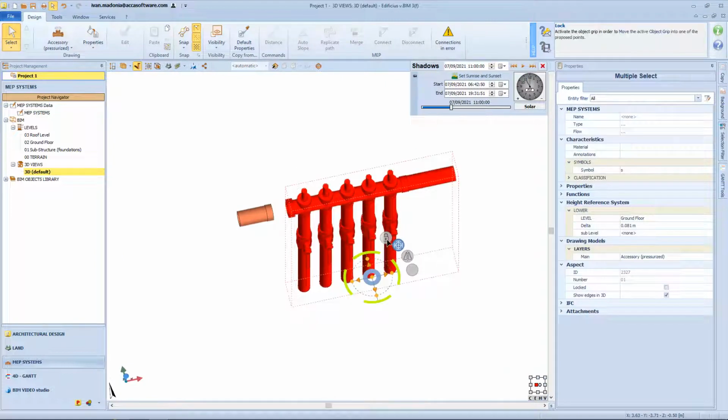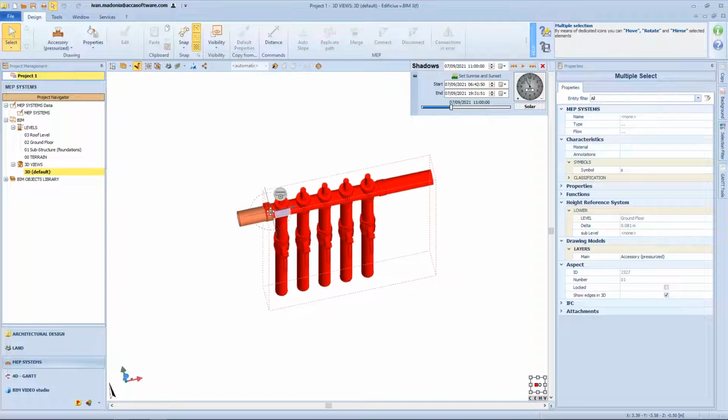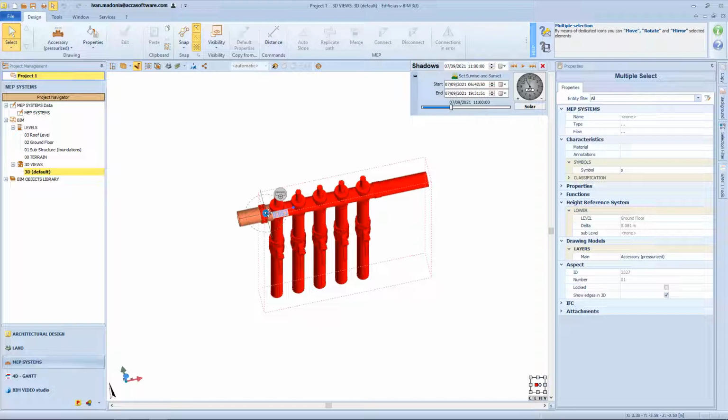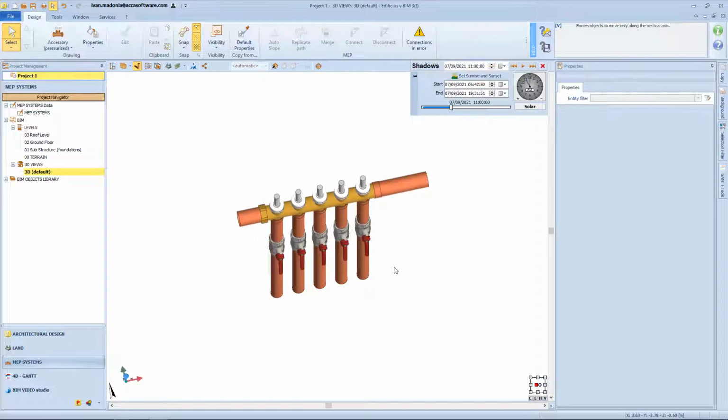Select different MEP objects. Unlock the multi-selection object grip with the padlock, and move it to a connector. If you then move the multiple selections in correspondence with a connection of another MEP object, the connection snap, in this case, is blue instead of yellow, as two MEP entities are not connecting, but a selection of entities, which represent a block on which automatic connections cannot be guaranteed.